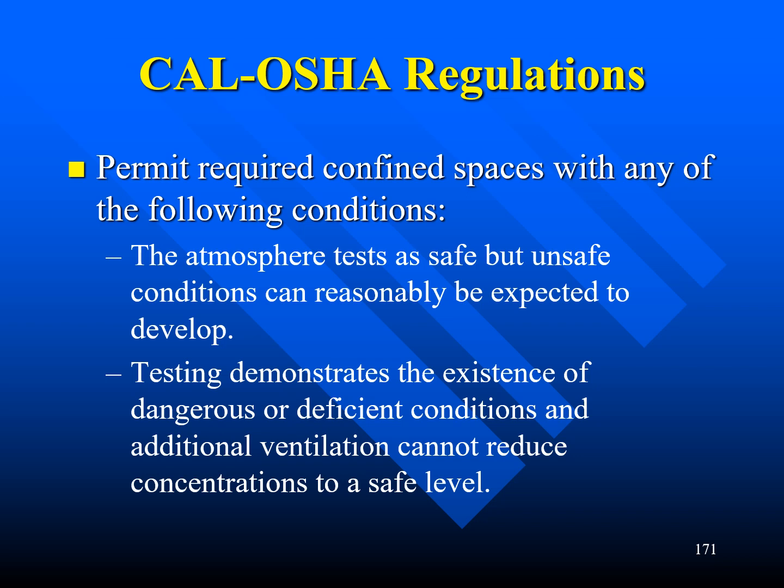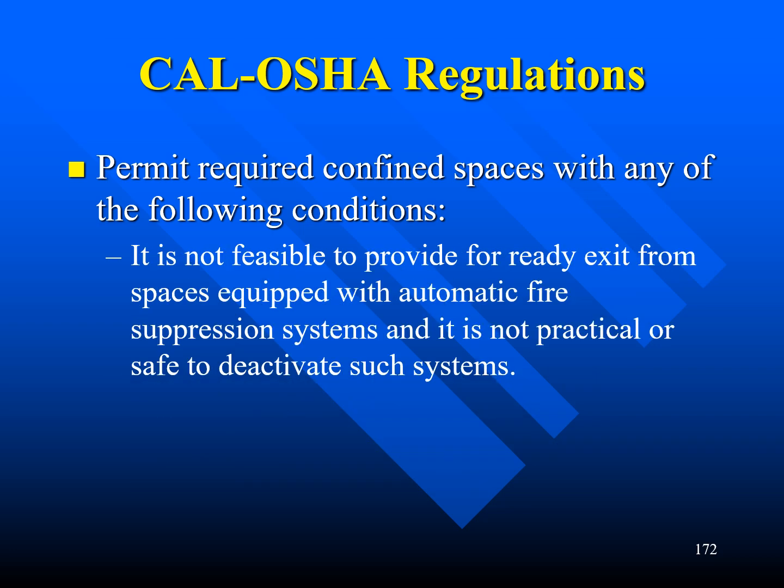The atmosphere tests as safe, but unsafe conditions can reasonably be expected to develop. Testing demonstrates the existence of dangerous or deficient conditions, and additional ventilation cannot reduce concentrations to a safe level. Or it is not feasible to provide for ready exit from spaces equipped with automatic fire suppression systems, and it is not practical or safe to deactivate such systems.